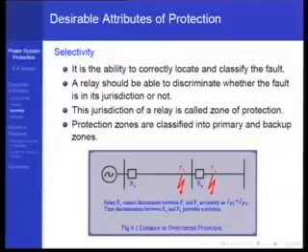If you had a redundant duplicating system there, it is of no use. Or a CT burst happens, and a CT is not duplicated, then what do you do? So making the local protection redundant automatically does not solve the problem of backup protection. So the remote backup is still very important.